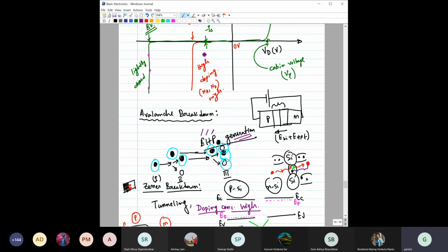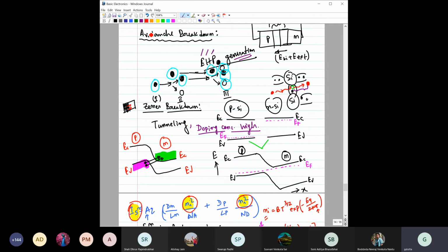So these Zener diodes are made with doping such that their breakdown voltage lies in the range of say 5 to 12 volts. This is the beauty of Zener diodes. Zener diodes are made to be operated in breakdown only. We will see it later on when we discuss breakdown.